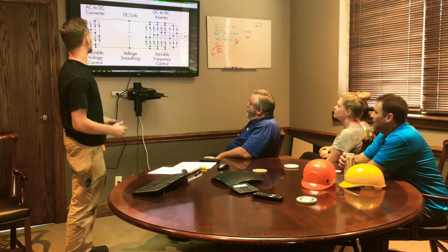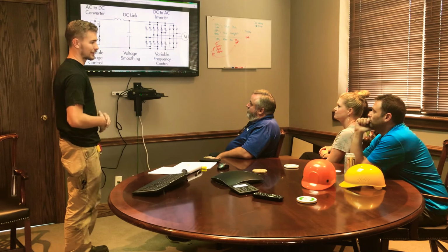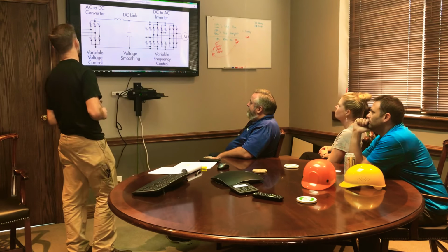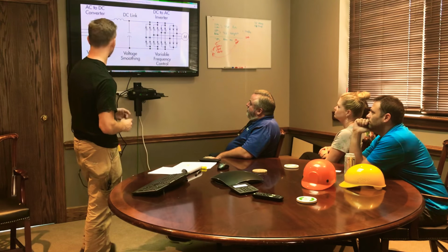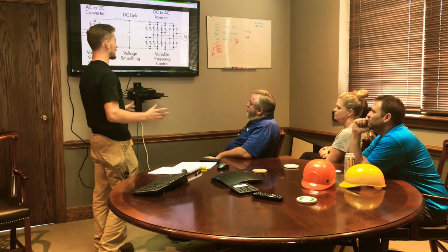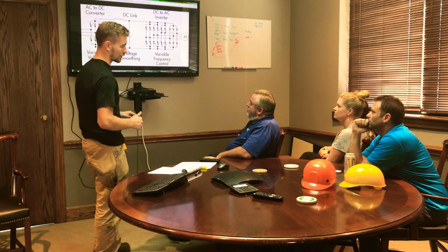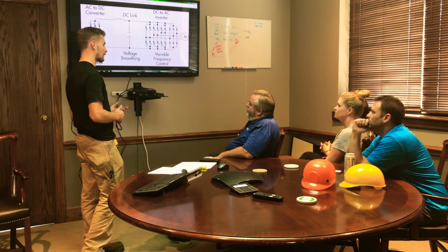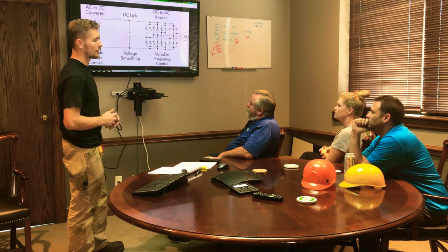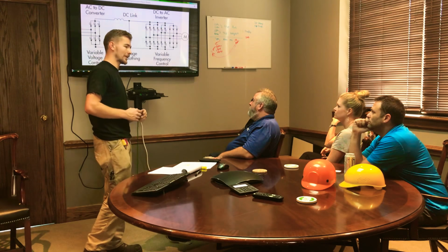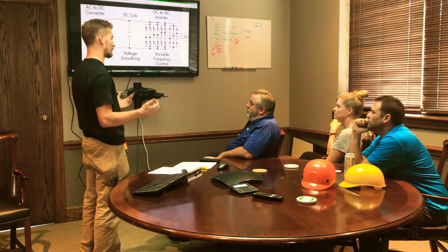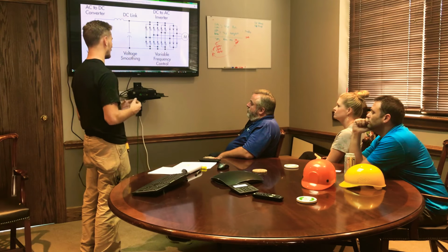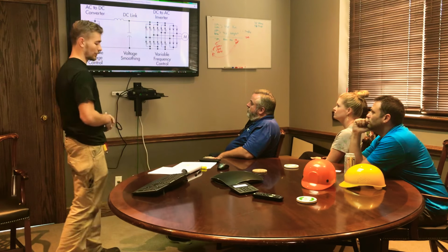So does anybody know what this circuit diagram is depicting? And don't feel bad if you don't. No one? Okay, so this circuit diagram is depicting a variable frequency drive. This is something used in almost any industrial alternating current motor circuit that you will find. It's very important because it allows for AC motor soft start and motor variable speed. It is extremely important to our location in particular because we have a lot of equipment on our machines that is expensive, and this allows us to control its speed without physically damaging any components.